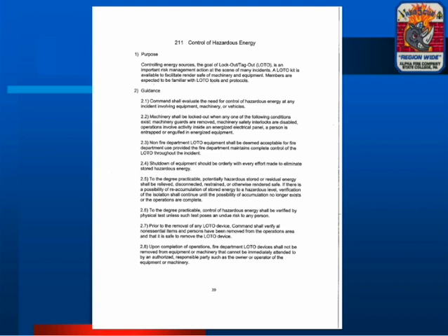Prior to the removal of any lockout tagout device, command shall verify all non-essential items or persons have been removed from the operational area, and that it's safe to remove the lockout tagout device. So even once we put a lockout tagout device on, that device may stay in place until maintenance arrives, or maintenance completes their operation, and then we work with them to remove the devices that we've added to that machine.